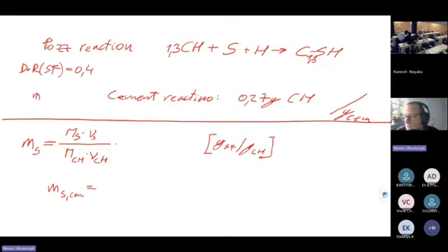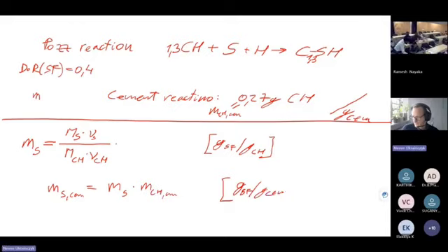Let's call this the mass of portlandite in cement. So if we have gram per gram of portlandite, and then we multiply it by the mass of portlandite in cement, we get the unit of gram of silica fume per gram of cement, right?